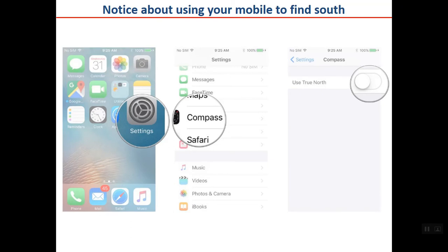Just one thing I wanted to mention here, and it's important because mobile phones generally have this capability. Just remember that whenever you want to use your mobile phone compass, go to the compass settings and put it on true north or true south if it is not so, because you should check what the default value is. If the default value is true north or south, then it's okay, but if the default value is magnetic north or south, then you should change it to true north and true south, and then use it for facing your solar modules or solar panels.